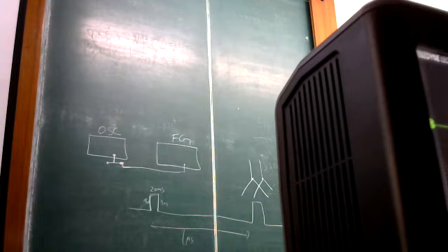This oscilloscope has one setting which actually allows me to change the input impedance of the instrument. Remember, in microwave frequency, we always have source impedance as 50 ohms and load impedance at 50 ohms, ideally speaking.